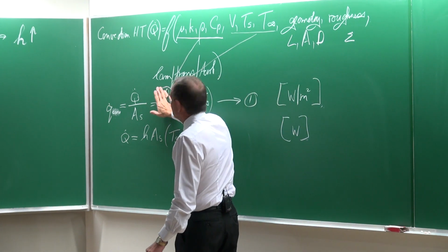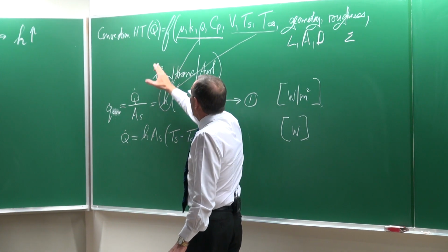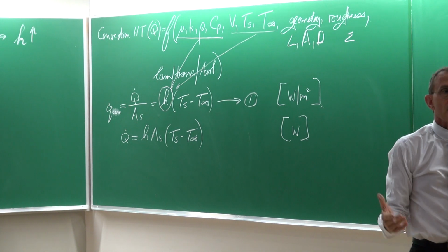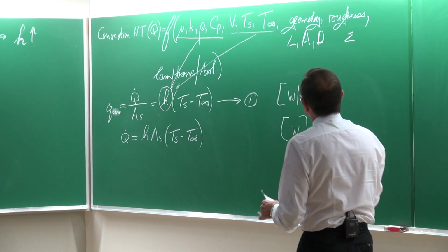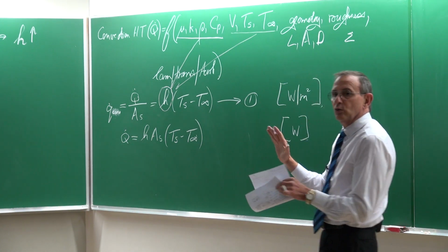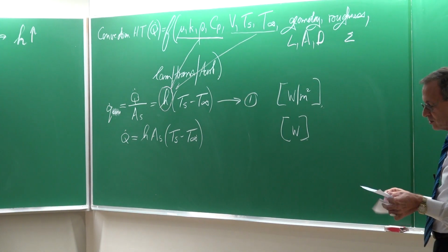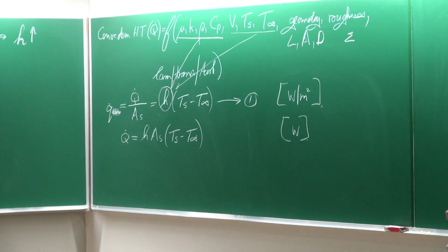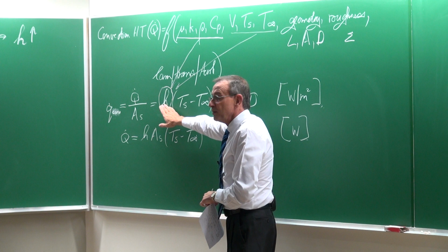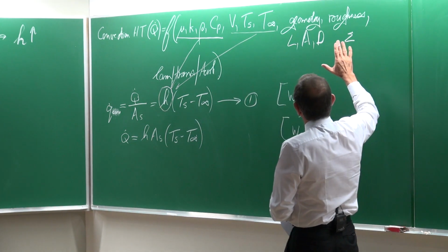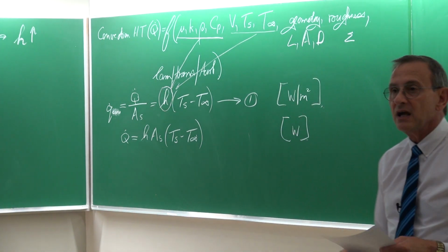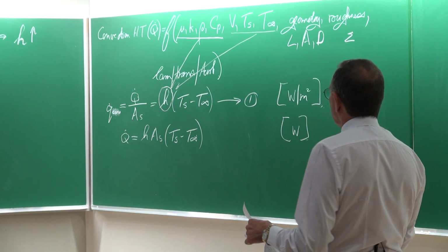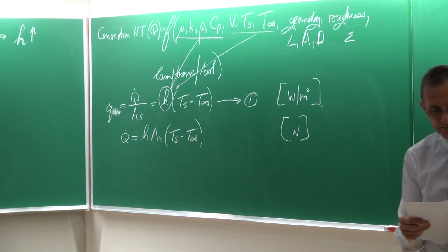We would actually like to take this heat transfer coefficient out and have the correct function. But so far, we have been unsuccessful in solving it analytically, and even with all the experiments we are doing, we have challenges of getting the heat transfer coefficient. And this function will be very specific to certain geometries as well as to certain flow regimes, like laminar flow regime, transitional or turbulent flow regime.